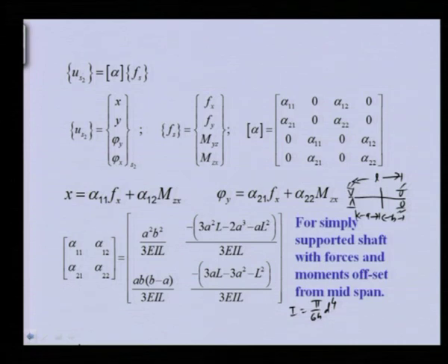Now we can write this displacement, which is due to the flexibility of the shaft, in harmonic and complex terms. The force we already expressed like this. So if you substitute this in the previous equation, we will get the shaft flexibility displacement at the disk related to the reactions at the disk. This is the previous equation only. So now we are writing it in the frequency domain.